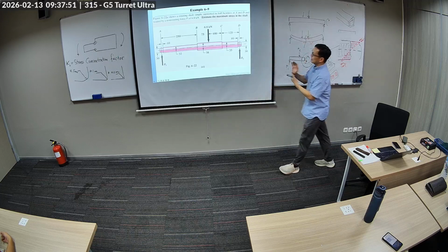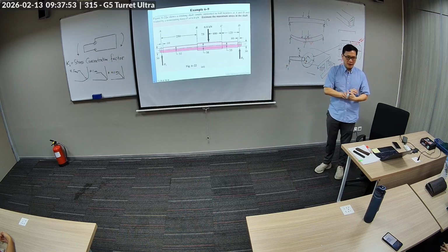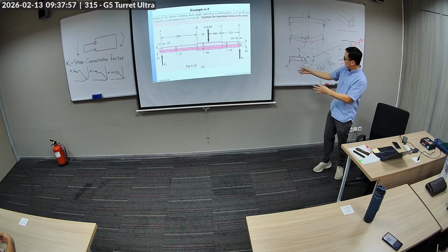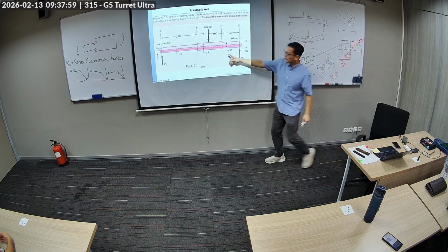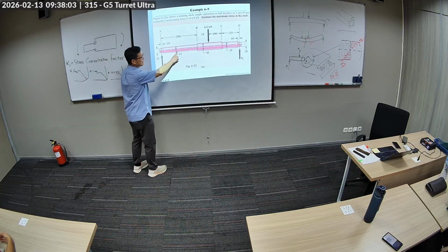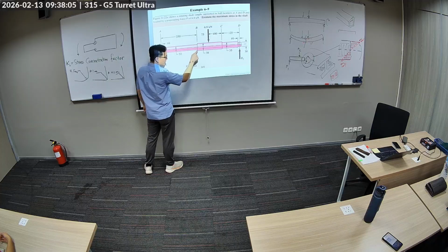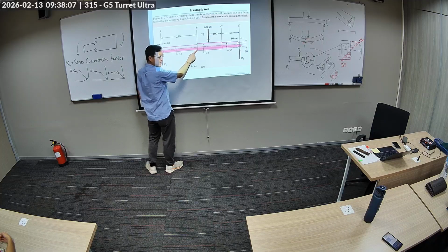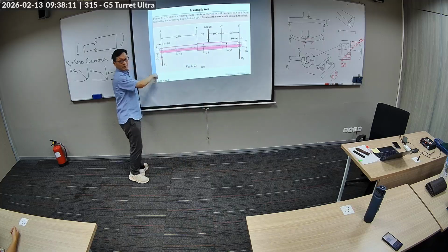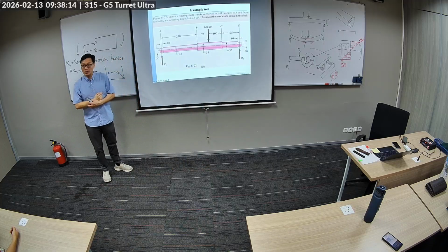Now this M will be the bending moment that will create the failure here. So when you're presented a problem like this, you are interested in determining the internal moment, not here, not here, because I know it's going to fail either here, or here, or here, or here. Those are my candidate failure points.